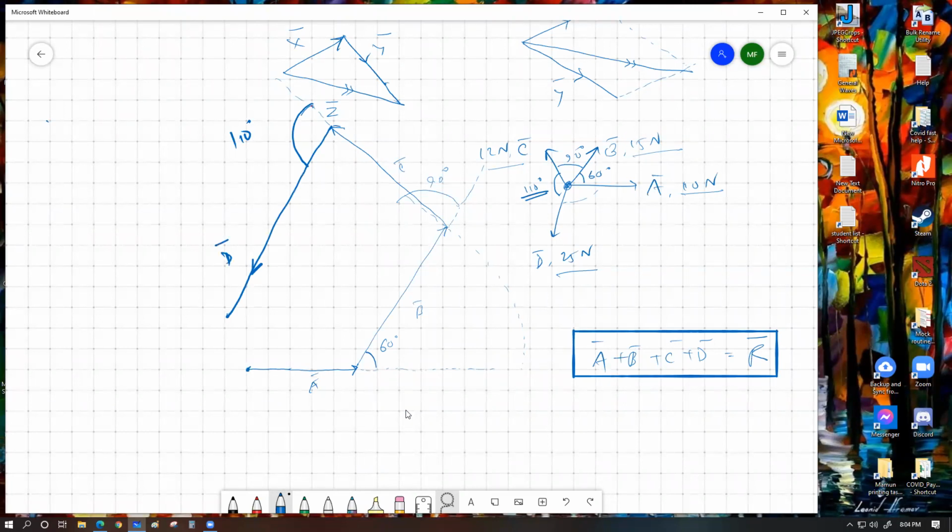So it's very much similar to how the triangle rule works. The way the triangle rule works is that you place the component vectors. Component vectors are the vectors which make up the resultant. So resultant is the vector which is the final output. And component vectors are the individual parts which make up the resultant vector. So if you place the component vectors one after another with appropriate scale and direction, then the completing side of the triangle gives you the resultant.